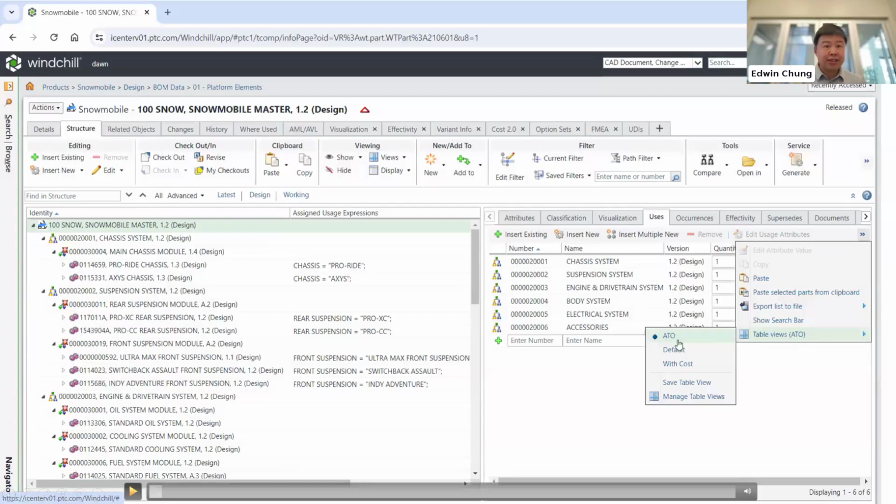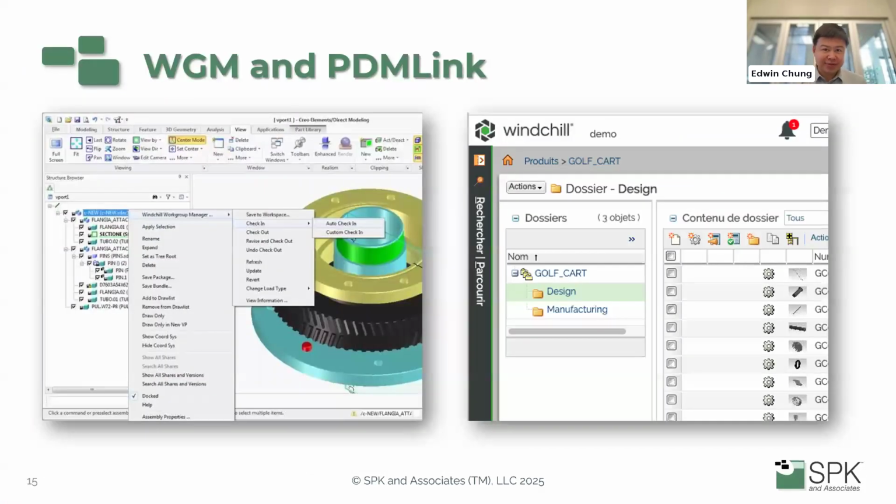So as we get into this discussion, let's talk about PDM Link. There are two key applications that we need to understand. The first is Windchill PDM Link. This is the piece that connects Windchill to PDM, product data management. It's a required component for managing and storing all of my BOMs, changes, configurations, automated workflows, et cetera, so that I have enabled my server to store a single governed source of truth. You can access it via web browser, which is very convenient and expected, a bare minimum nowadays. And to connect into PDM Link with Creo, it's actually built in. Creo comes with a built-in integration to Windchill PDM Link.